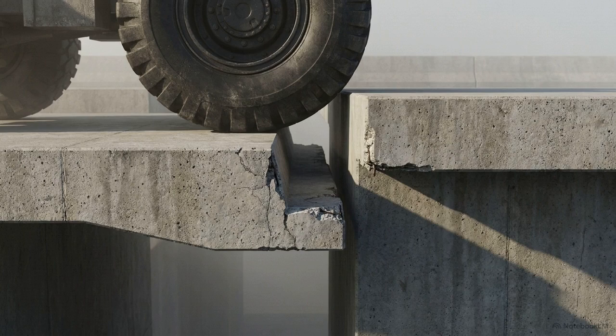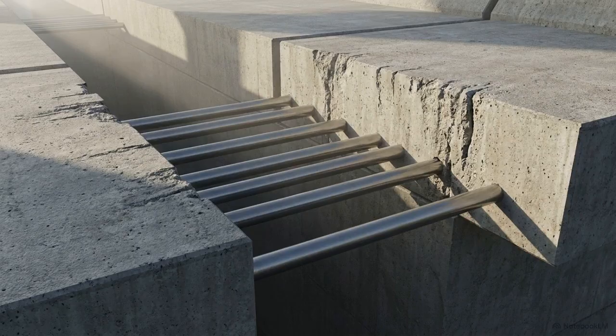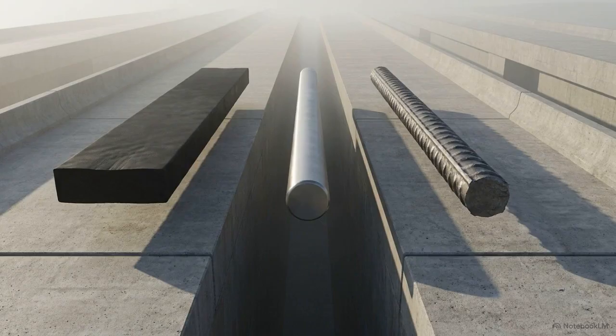This creates a central engineering paradox. The pavement must be physically severed to relieve thermal stress, but at the exact same time, it must remain structurally connected to transfer heavy traffic loads across the gap without differential settlement. Resolving this contradiction requires a precise combination of joint geometry and specialized steel embedments across the cut. A durable highway is achieved by categorizing physical forces and isolating them with highly specific, mechanically distinct joint types.